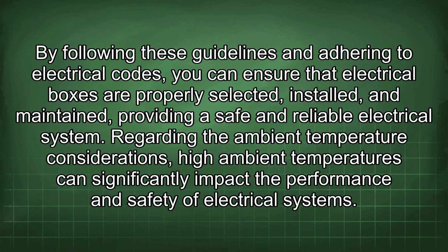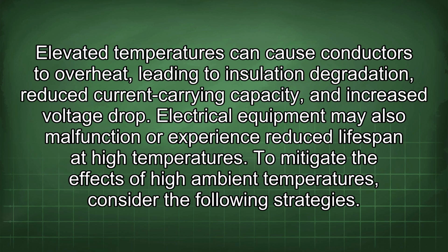Regarding the ambient temperature considerations, high ambient temperatures can significantly impact the performance and safety of electrical systems. Elevated temperatures can cause conductors to overheat, leading to insulation degradation, reduced current carrying capacity, and increased voltage drop. Electrical equipment may also malfunction or experience reduced lifespan at high temperatures. To mitigate the effects of high ambient temperatures, consider the following strategies.